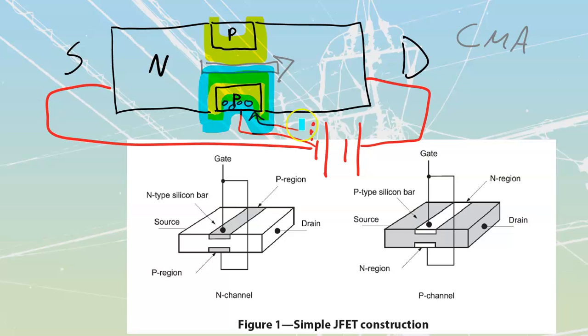As I increase the amount that I am biasing against here, the more that I'm closing this down, which means the more that I am dropping that circular mil area. And as the circular mil area goes down, the resistance goes up. So I can drop more voltage across from this end over to this end, particularly if I had another load connected in line with this. We'll take a look at that in a second.